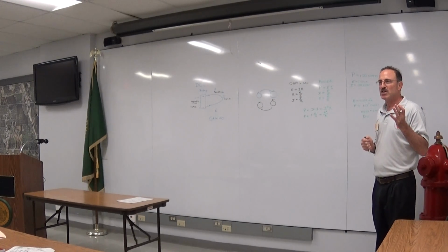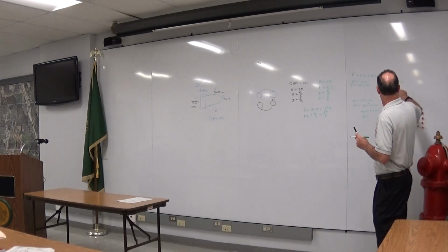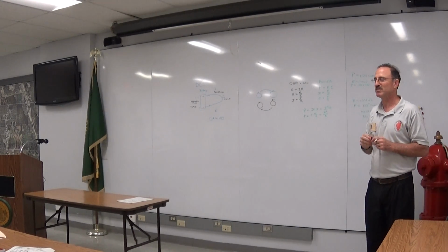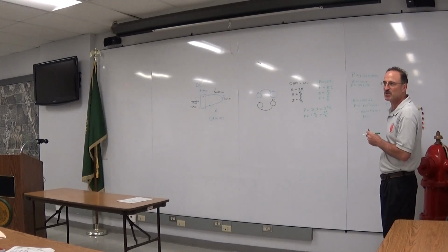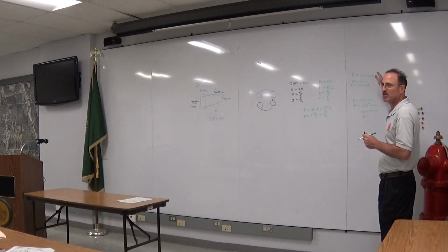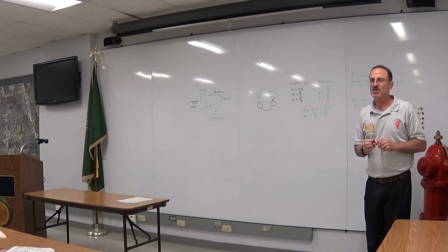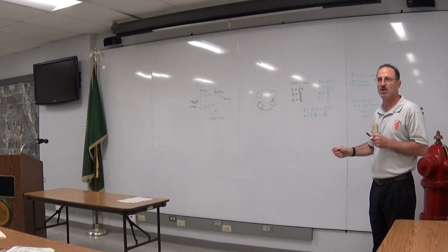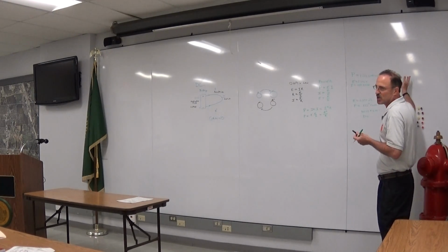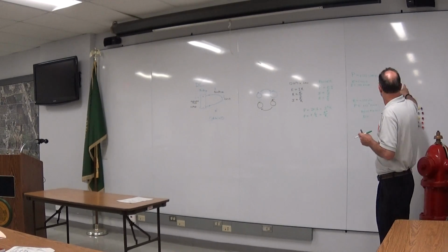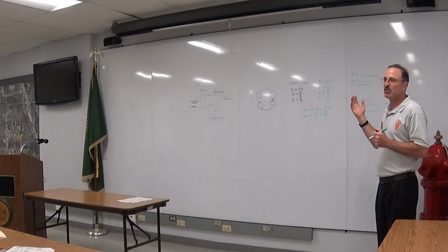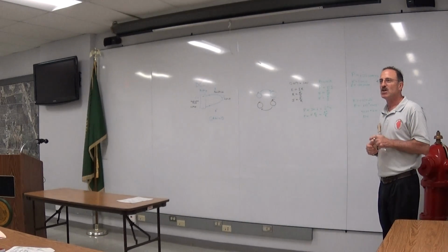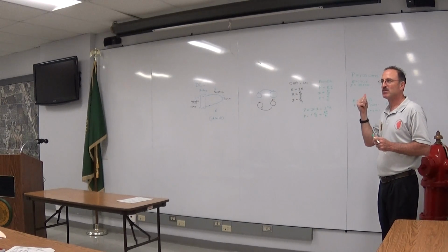Well, that's what they did. But they couldn't do it with DC, because if they were to give you too high a voltage in your house, you tend to get electrocuted more often. My choice of voltage isn't good because that's actually what you get. But let's multiply everything by 100, and you'll see that it's impractical to put such a high voltage in the wall. So they made a standard, it was 120 volts in this country. But if they put 120 volts over the wires with resistance, they'd lose a lot of heat. So what they do is they jack it up to thousands of volts.